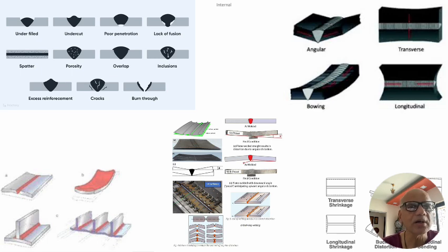The second defect is undercut, which is also a surface defect, and the welder will find it, only an experienced welder will find it while he is welding through his screen, but otherwise a new welder may miss out, especially the small fine undercuts which emerge on cooling. After cooling, in the heated condition, you feel as if you have done a good weld, but when it cools down you see that there is an undercut, sometimes a sharp undercut, which can be a stress riser.